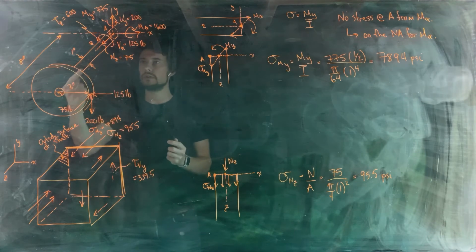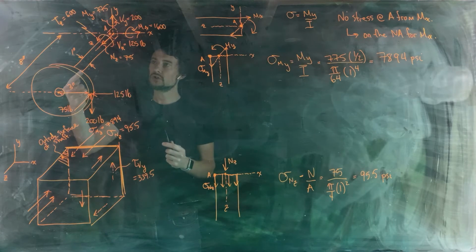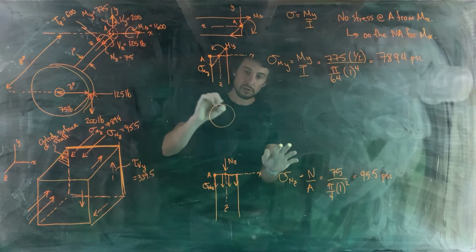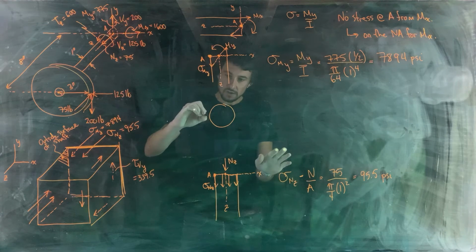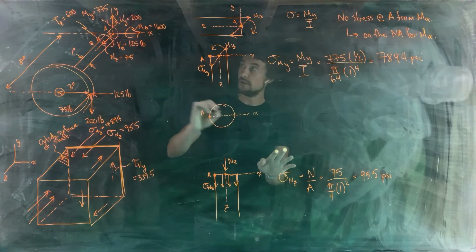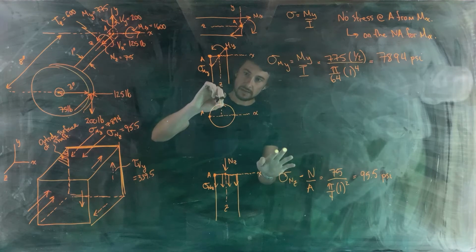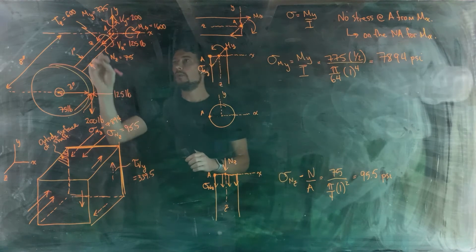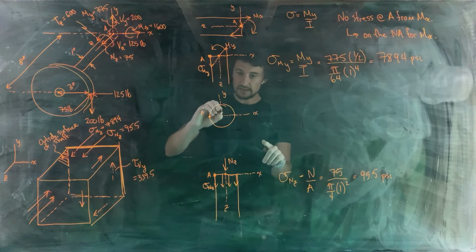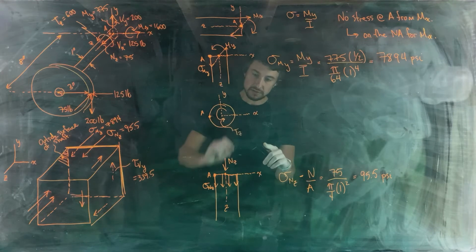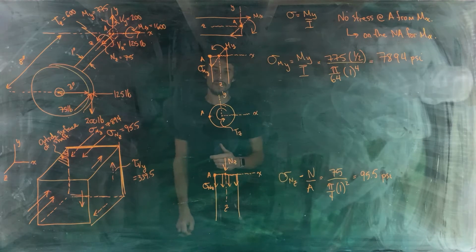All right, one final one to do, and that is the torque about the z-axis. Again, look at the object or cross section down the z-axis, since we've got something that's occurring about the z-axis. So looking down the z-axis there, our cross section is looking like this with point A there, and the x-axis coming out this way, y-axis upward like that. And what direction is Tz in? It's occurring around in this direction. So our internal torque T subscript z is like that.